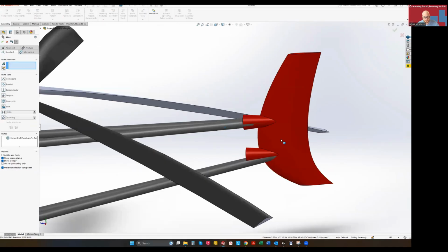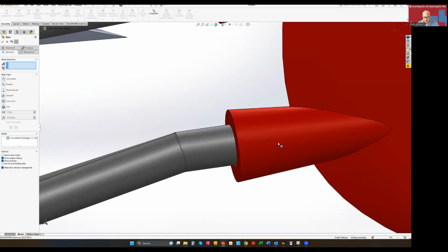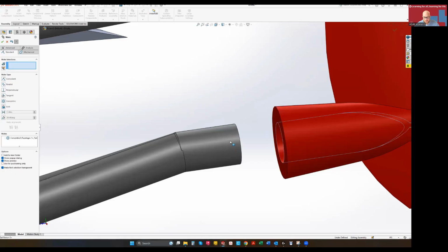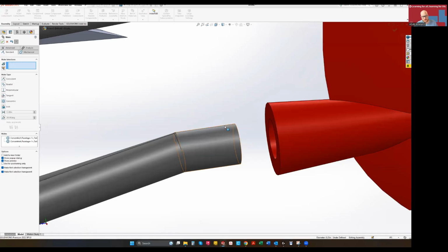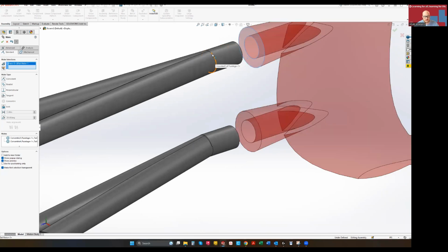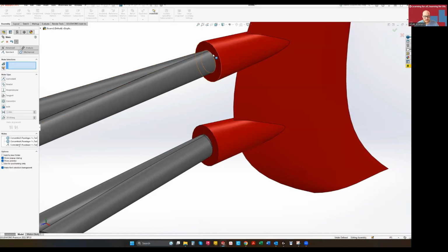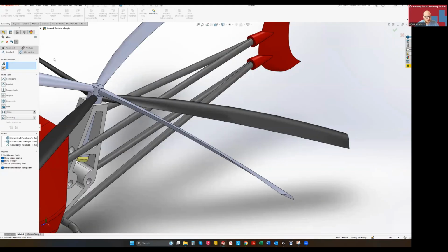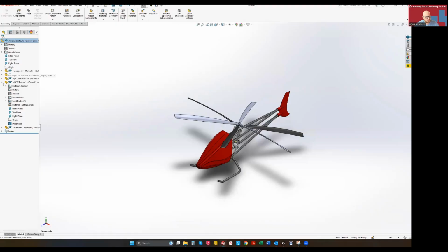There we go. I'm going to just kind of drag this back. We need to do the same thing. So just kind of drag this away. Click, Control, click. Click the green check mark. And then from here, I usually just take this face and I will maybe select this point. Just like that. And we're going to click OK. So those are just going to be coincident. That point's going to coincide with that face. X out of your mate, or escape out of your mate menu.